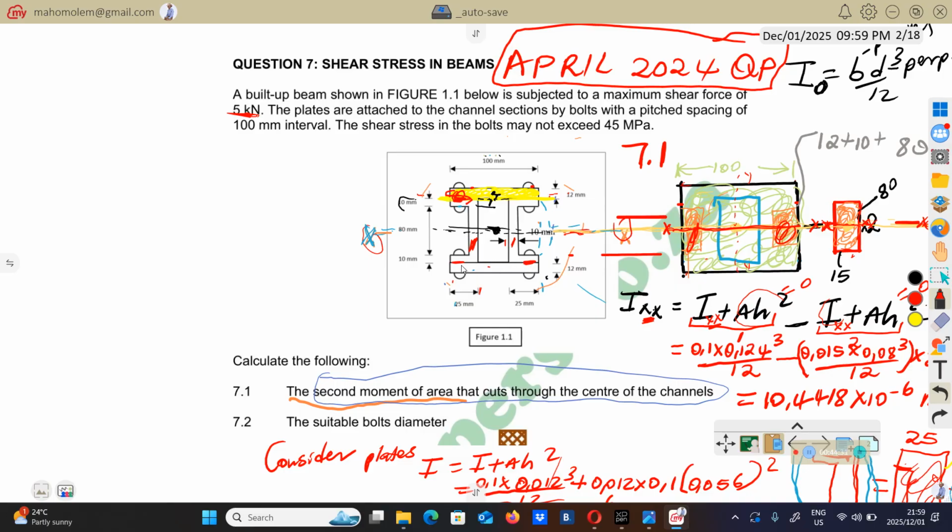So that's why we're going to have a single shear, meaning that if the force in this bolt is big enough, then this nail or whatever is going to fail due to shear. When it fails, it's going to slide like this. So that sliding is the shear. It's going to shear at this point. So we're going to have a single shear there. Right, c is going to be 1.